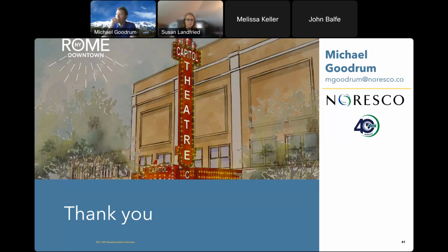Yeah. You can't do a cool roof when you have a slate roof. Right? And air sealing is really a problem if you have a big 2-foot wide stone foundation that the building's sitting on. And I don't know where we'd fit insulation, given that the entire basement is already built out. I mean, we'd be talking about taking off the walls or something. So it just seems very limited for certain buildings.